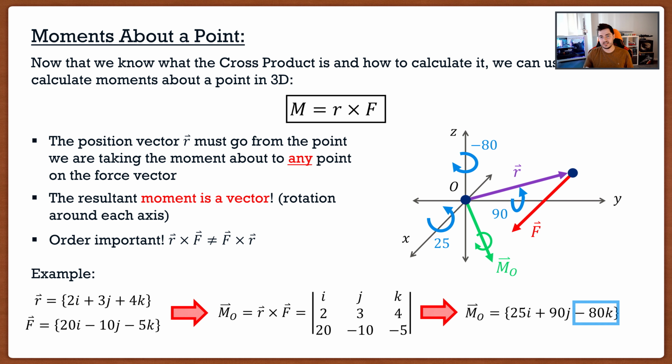So again, I just want to say it one last time so you guys know. Moments in 3D, cross product. Moments in 3D, cross product. If you guys know that, you guys will be absolutely fine in your midterm or final question. Again, the only trick, make sure the position vector is before the force vector when we cross them. Order is very important.